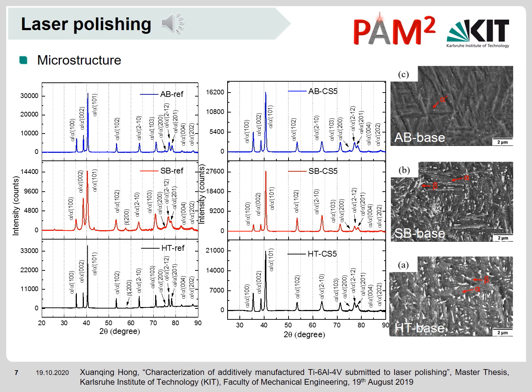The investigation of the microstructure evolution showed that the laser polishing altered the microstructure of samples previously submitted to heat treatment, while no changes were observed in the samples as built submitted to laser polishing. The resulting microstructure after each process was linked with properties such as hardness and residual stresses.